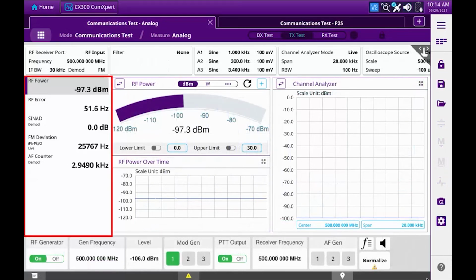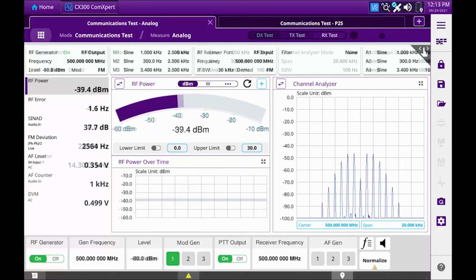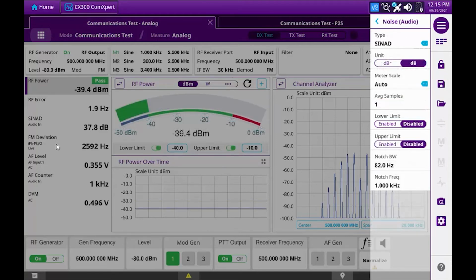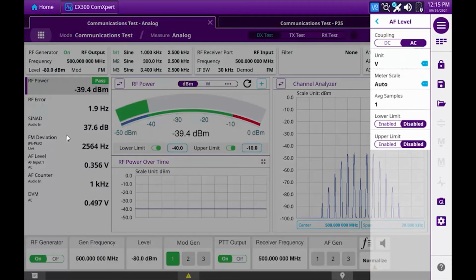The meter reading pane provides a quick view of meter readings. The meters displayed in this area depend on the mode of operation, the demodulation type, and noise meter selections. If a meter is selected for display as a swept meter, the meter display in this pane will have a gray background. Like the Test Settings toolbar, the meter reading pane provides a means to directly select the submenu that controls the settings of the meter simply by selecting the meter. Color-coded pass-fail states are visible in this pane for any meter that has its limits programmed and enabled.